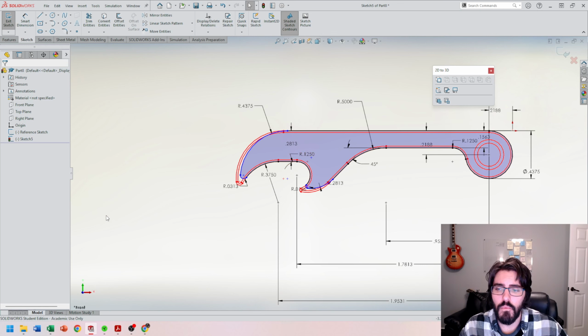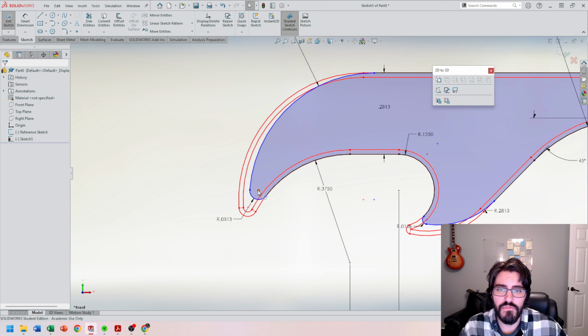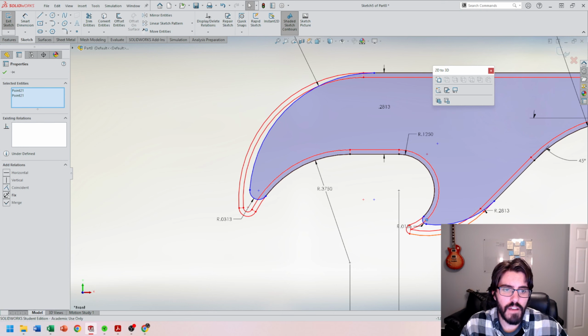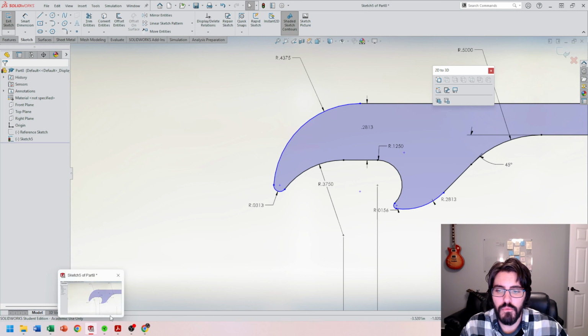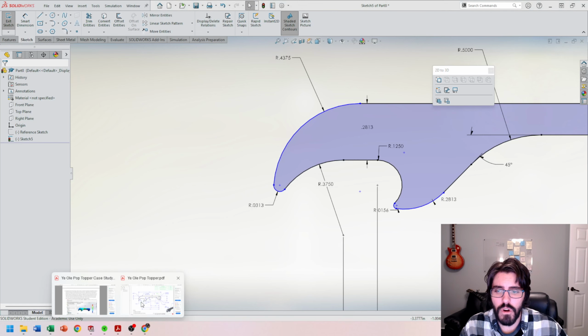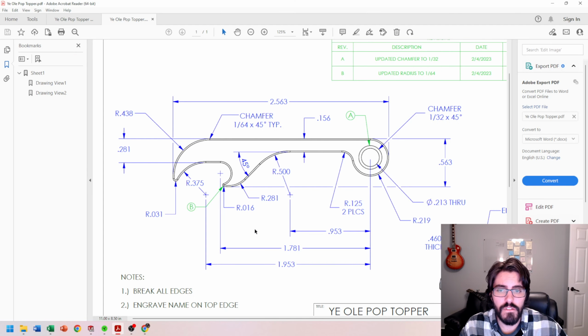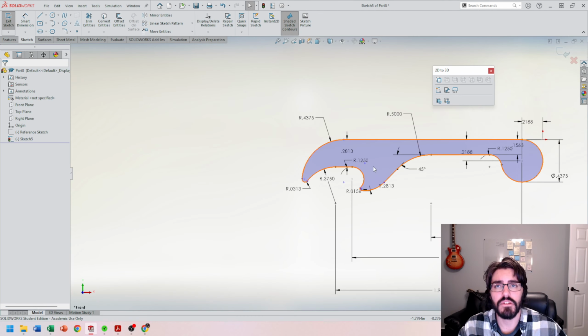underdefined areas. And what I'm seeing is that I don't have the full extent here, or I don't have the full extent here. And what I'll have to do is establish a pretty tricky dimension for us. And we're going to do it in the same way that we just did all these center mark to center mark. And then we're going to fake it out and then use the properties command to do max to max. So what I'm going to do is dimension this arc to this arc here, and then place that dimension and then change it.